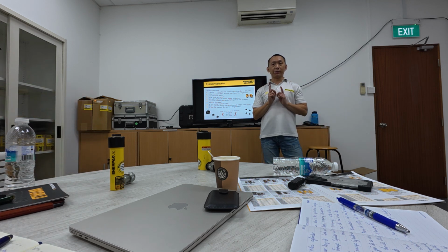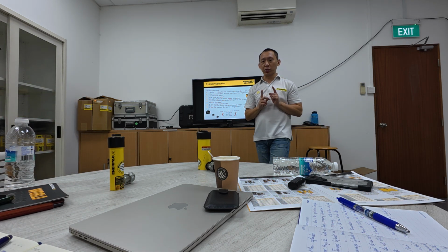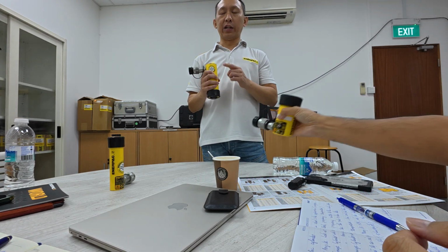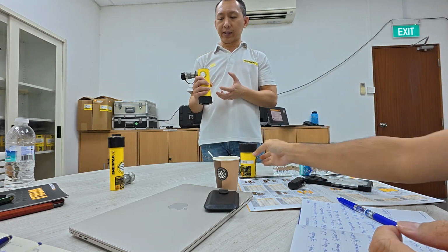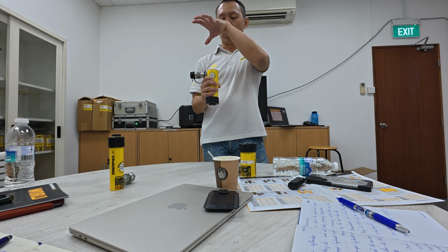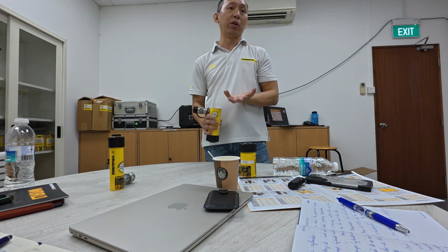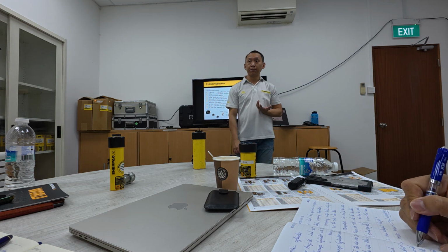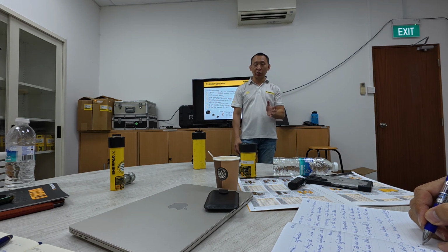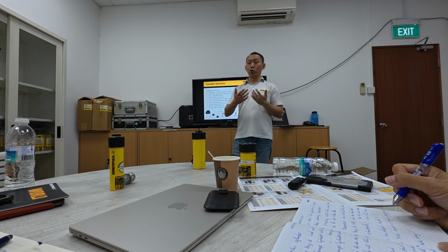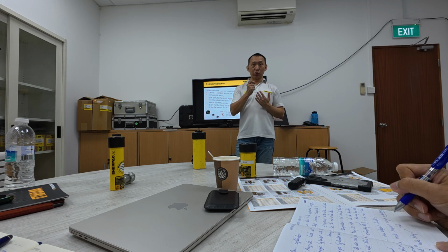Okay, it depends on how the customer uses it. We have come across customers who use it inverted this way for single acting. They make use of it in the system, because if it is load return, the load on the equipment will return on its own. We have encountered such applications before. So it really depends on how the customer wants to use it. I'm not saying cannot. It can be inverted, but of course take note there's a load return, so the customer needs to know what they are using it for.